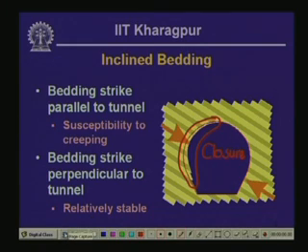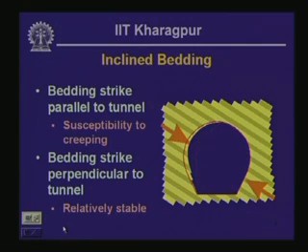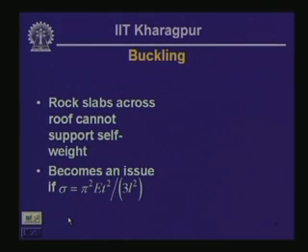Here the rock that was transected by the tunnel was basically phyllite, which is a ductile type of rock, and the tunnel was affected by closure as well as another type of problem which we are going to see a little bit later on. Then the third problem that we are going to get is in the case of tunnels constructed through rock which are laminated, and the laminations are inclined.